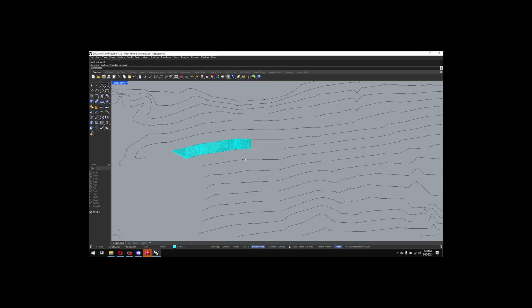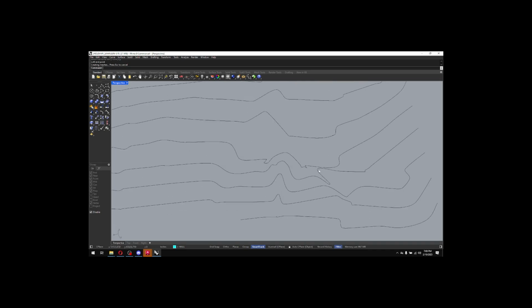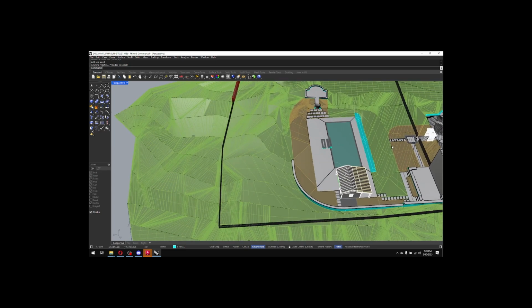So yeah, if you have to split a contour up a little bit, go for it. Again, not a big deal. You can imagine this would get really complicated down in here, unless this was an area where you had to have an exactly perfect model because you're taking measurements off of it. You might have to rebuild this a little bit or get really fine lofting in there. Otherwise, patch the whole thing. Keep moving. Don't worry about it. Again, this area over here is not the focus. The focus is where your cameras are going to be.